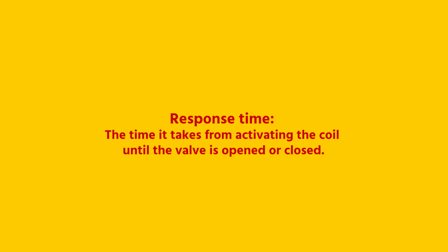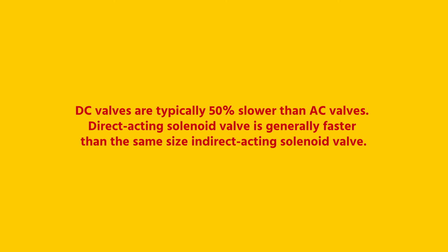Fifth is the response time. Solenoid valves are known for their quick response time. The response time is expressed in the time it takes from activating the coil until the valve is opened or closed. DC valves are typically 50% slower than AC valves. A direct acting solenoid valve is generally faster than the same size indirect acting solenoid valve.